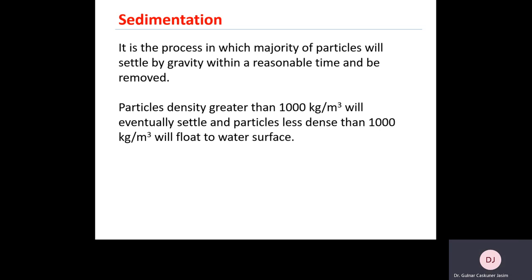Sedimentation is the process in which the majority of particles will settle by gravity within a reasonable time and be removed. Particles with density greater than 1000 kg per meter cube will eventually settle, and particles less than 1000 kg per meter cube will float to the water surface.